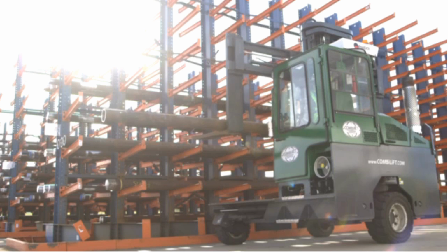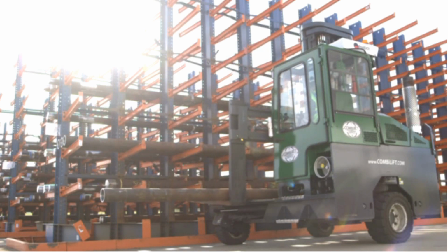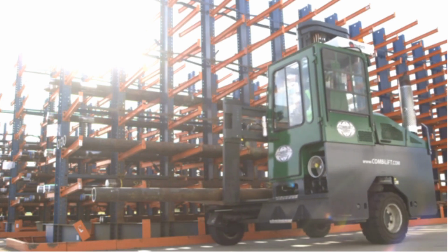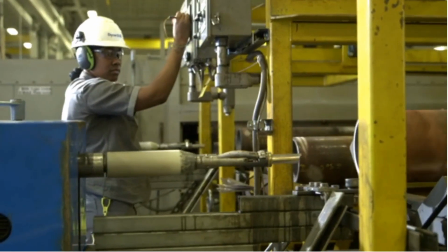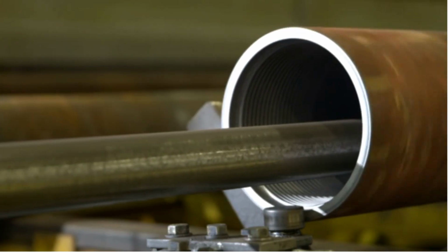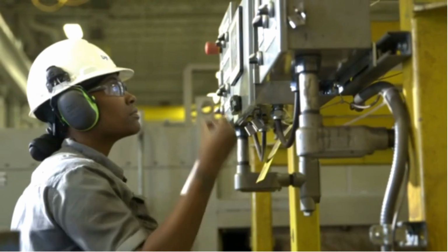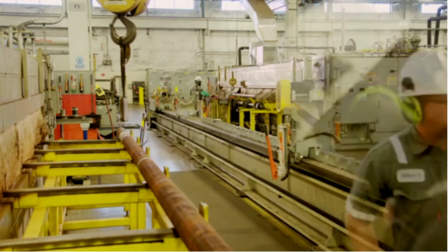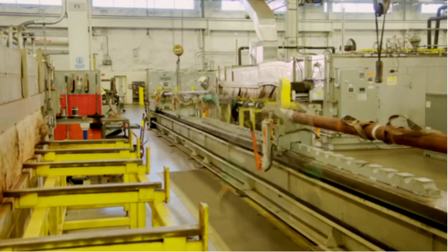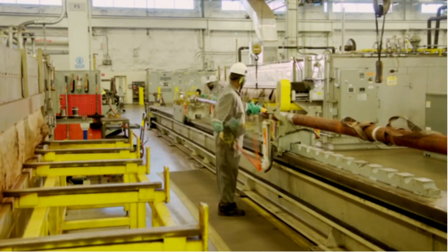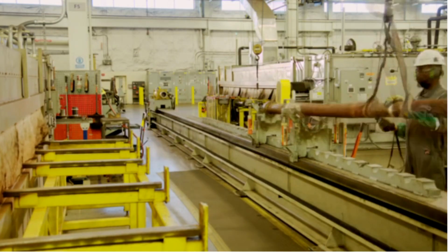After inspection, the tubes go to a supermarket kanban that allows the planning team to schedule a single piece flow to coordinate core mold use and maximize customer deliveries. Directly after surface prep, precise application of cutting-edge adhesive compounds provides a strong chemical bond between the stator and elastomer. The stator is assembled with the molding core using custom-fit tooling based on measurements taken in the prep cell. Critical assembly data is recorded to verify conformance to standards.